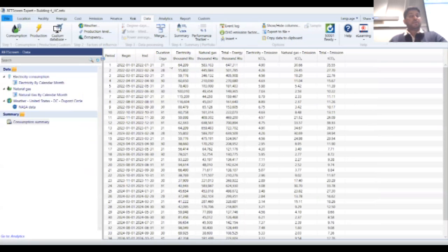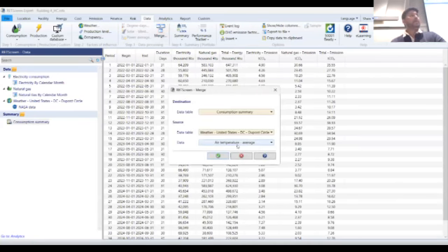There you go. So now I have my period, my duration, my electricity, natural gas in kilo-BTUs, and my total energy combined with my emissions. But now I want to compare the total consumption with weather. I cannot use heating degree days and cooling degree days both. I cannot just simply add them together, but I can compare it with air temperature. So again, the same, I'm going to merge the consumption summary.